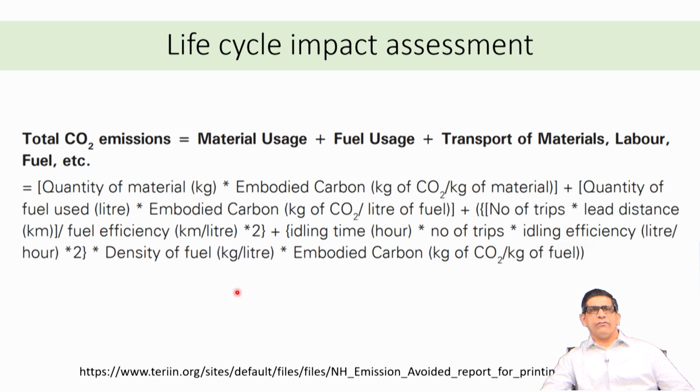Then based on that you come up with your life cycle impact assessment, which is the total CO2 emissions from material usage, fuel usage, transport of material, labor, fuel, etc. You can look at this equation, and that is how it has been calculated. As has been mentioned earlier as well, this LCA is nothing but an environmental accounting exercise. As you can see over here, it is essentially accounting.